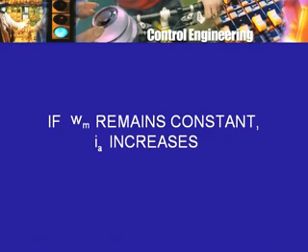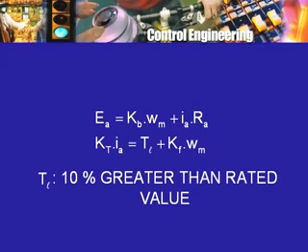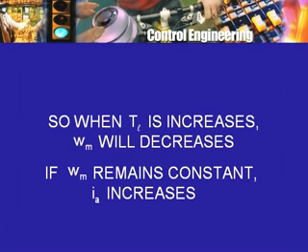The motor torque comes from the armature current, so the armature current will have increased. Now, if you look at the electrical equation, the armature current increases the armature drop. Now, if the armature drop is increased, the supply voltage is the same, then the back EMF will reduce a little bit, but the back EMF is proportional to omega m. So, what does all of this then tell you? This qualitative analysis then tells you that when the load torque is increased, my assumption that the angular speed will remain constant will no longer be justified.